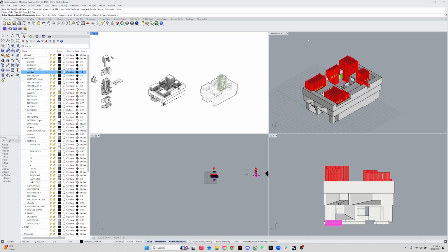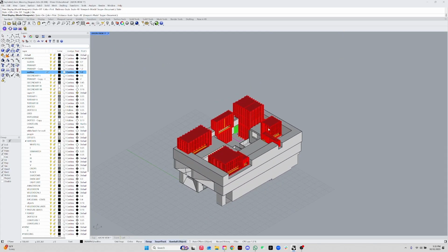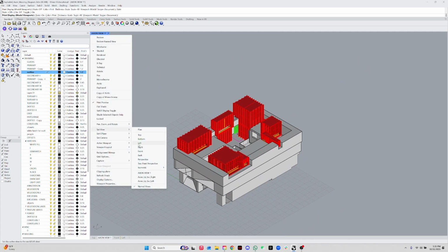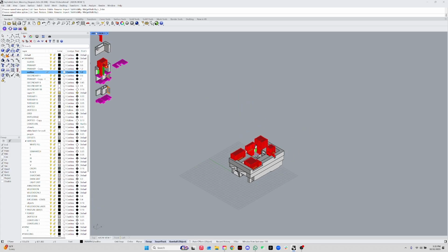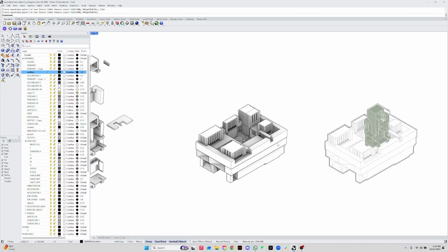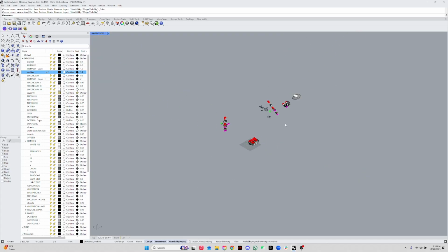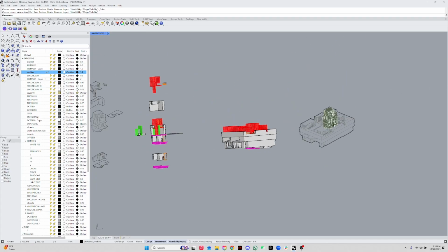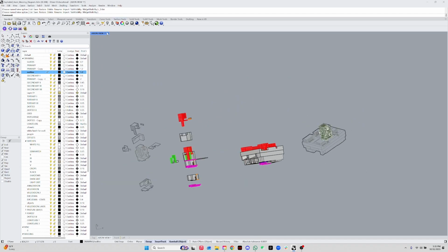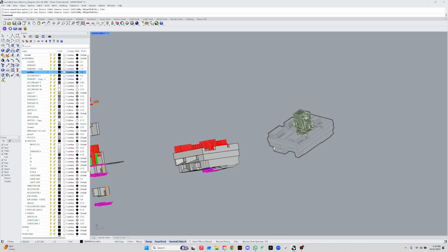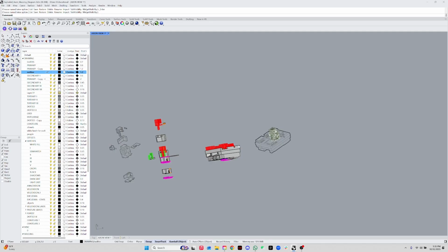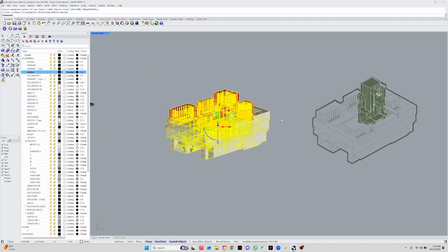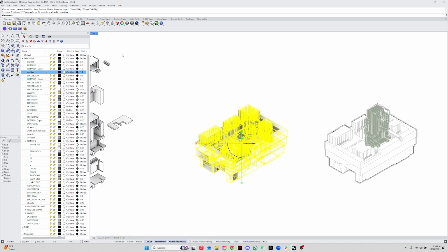So now let's go back to that view that we had. The first thing that we want to do, again, is make sure that I'm in my view. And there are 2 ways to do this. We can either do it this way, or we can do it with the model already rotated in top view, which looks like this, right? Usually, the generic view of an axonometric in Rhino is a 60-30 angle, so it's a 60-30 isometric view. So right now I have my 3D model in a 30-60 isometric view. Both are rotated, and the top view is basically almost like a make 2D, right?